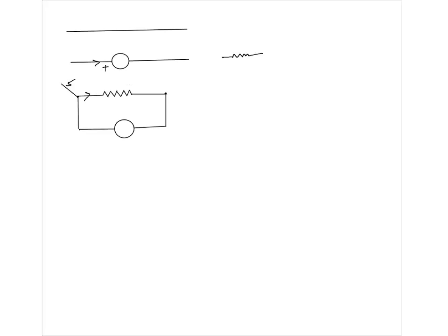But then the potential difference across the 2 points would obviously change. From Ohm's law, V is equal to IR. Now 4.5 R is clearly different from 5 R. Characteristics of the circuit are changed. You don't want that to happen. So ideally speaking, your voltmeter should take nothing: 0 ampere out of 5 ampere. All 5 amperes should continue to go through that resistor and you get exactly the same answer.